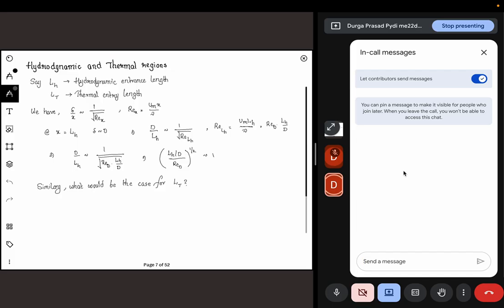Now, as I said, before going to the Prandtl number, first let's understand the hydrodynamic entrance region, and then we will see the thermal entry length. For the hydrodynamic entry length, how do you determine it? The entry length is the distance over which the external flow kind of assumptions prevail, which means we can still use external theory, the boundary layer theory that we developed before.